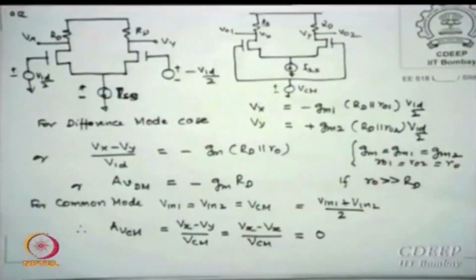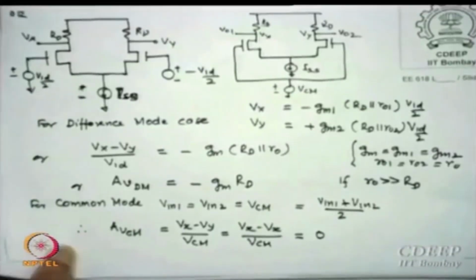So if you only pick up the output here, you will see a noise reading riding on it, in fact an amplified noise, but the other side is riding the same way. So if I take the difference, the common part will cancel, and that is how we say noise gets cancelled. Please remember, if I make a wrong statement, which you are very smart to catch immediately, I am never saying that Vx is 0 or Vy is 0, I am saying Vx and Vy are equal. That is the statement I make. Even if there is some issue, please come back. Is that okay?